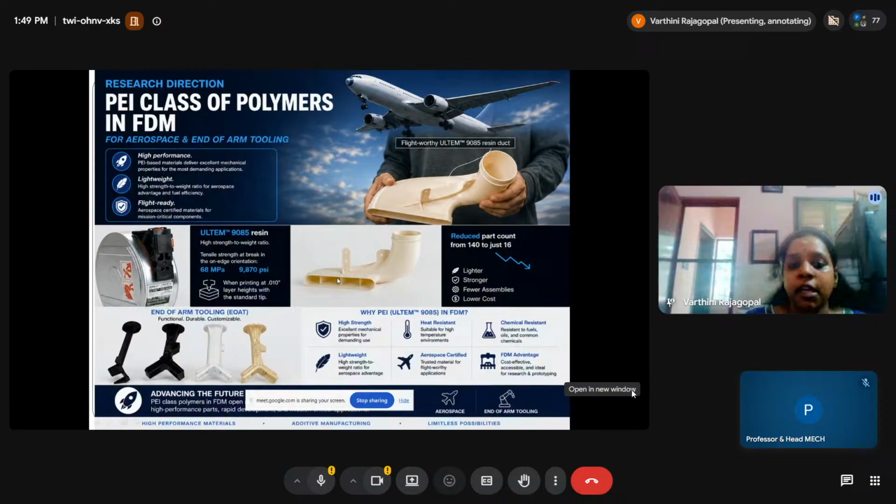So the problem here is, when I use a titanium implant, most of the stress will be acting on the titanium. So the bone around that implant will get weaker. Stress reduction happens, and the bone around that implant starts to not perform its function. This is actually known as the stress shielding effect. That will result in failure of the implant. So you have to do revision surgery. This implant will work only for 10 years, and after 10 years you have to do revision surgery to make it work better.